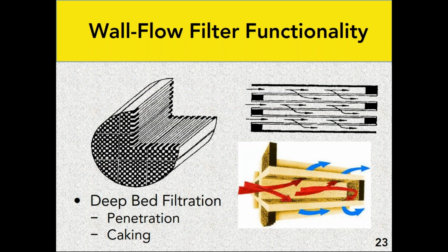Here's a little bit more of a blow up. You can see what's happening. I see the air coming in, you can see the plugs, you can see the exhaust gases going through, and you can see the particulate matter being deposited inside the channel itself. Now, what do we do with this particulate matter? Because when it gets to a certain point, it will plug the filter and it will prevent airflow from the